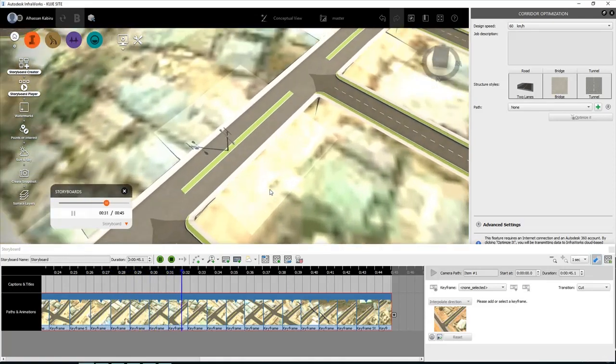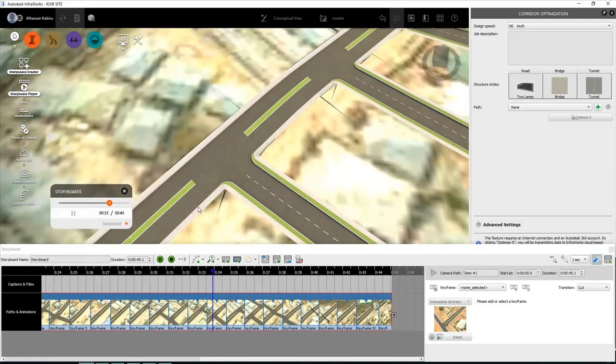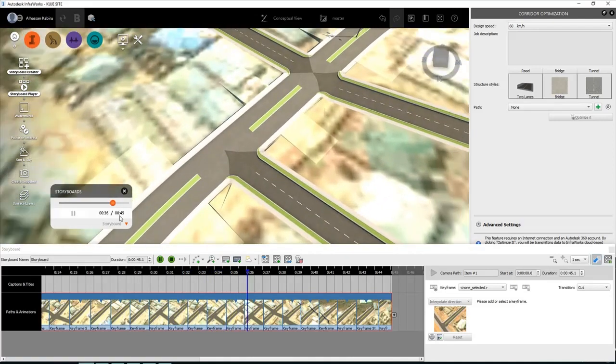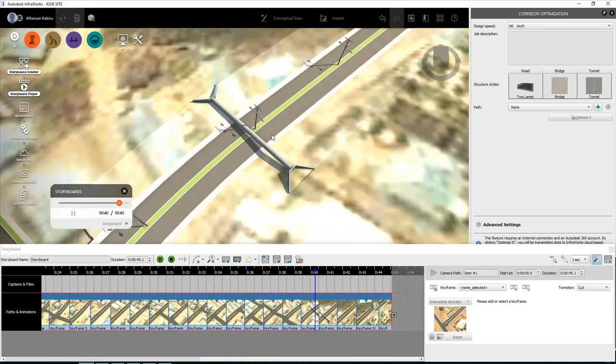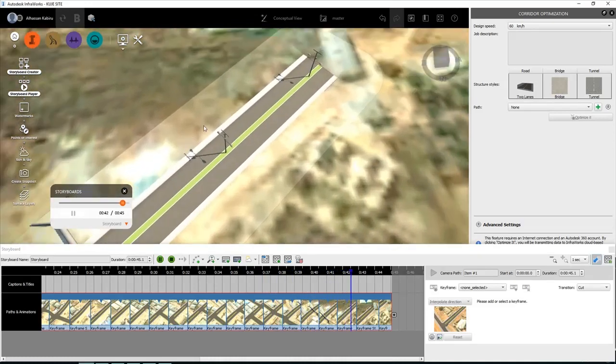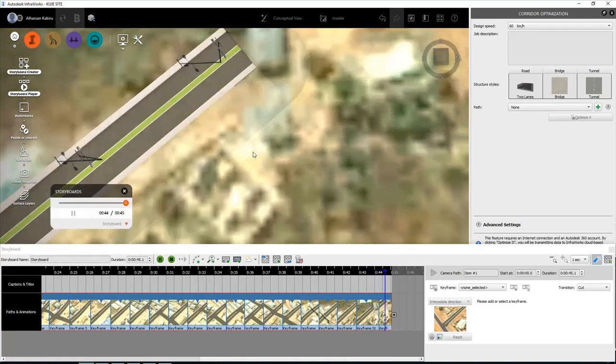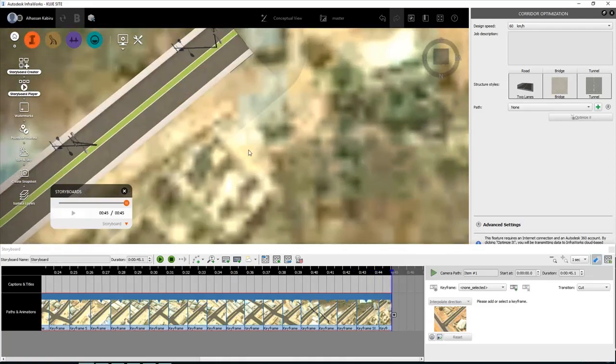So when you're able to check your walkthrough, you can now determine to export this into a video, convert it into a video component if you are okay with it. In this case, we're trying to put covers, but as I said, part three of these sections will focus on all the auxiliary structures: how you can create road components where you put your cover type for the pipe culvert, for the bus culvert, and also the drainage patterns for the underground piping with their manholes and collection points.